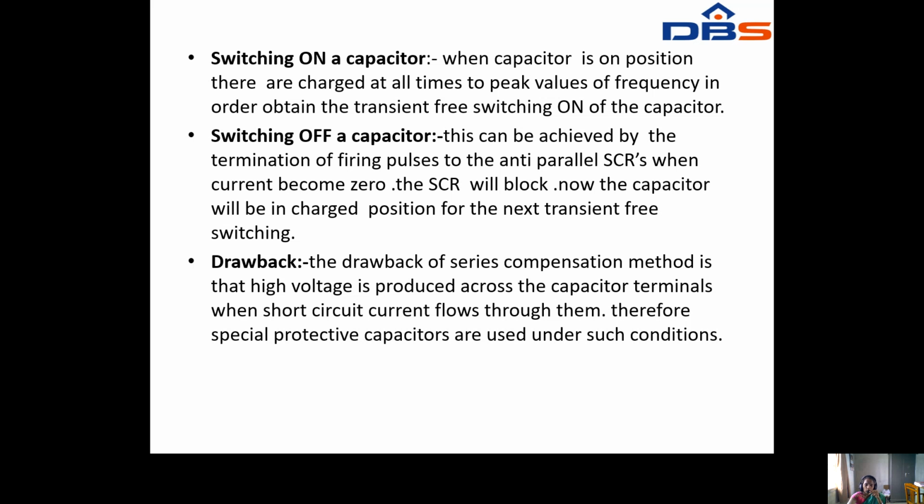First, switching on a capacitor. The capacitor will be switched on in the TSC. When the capacitor is switched on, it is charged at all times to the peak value of the supply voltage, in order to obtain transient-free switching on of the capacitor.